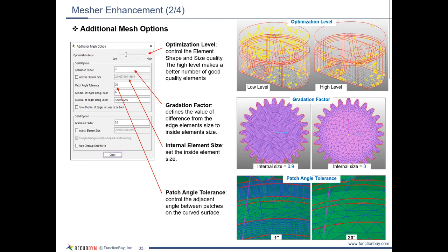So we really want to have the best quality on the outside. For example, when you do a hex dominant mesh, it'll tend to have pretty much 100% hex elements on the outer layer, and then as you go towards the center, it may have to introduce some other elements here and there. But that's providing the best results in general.